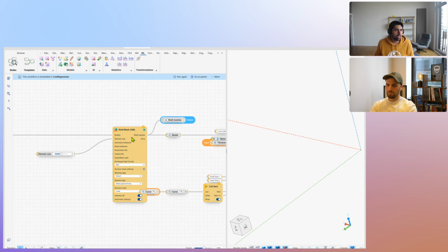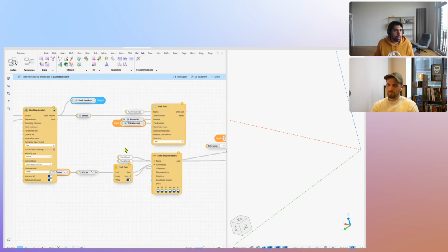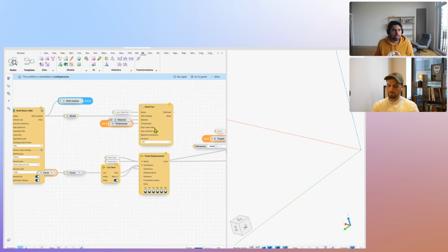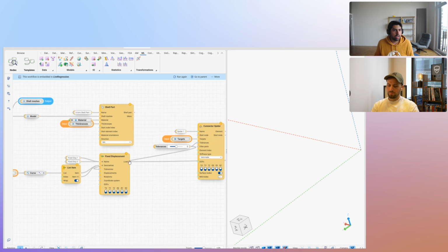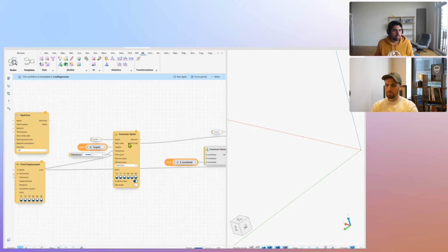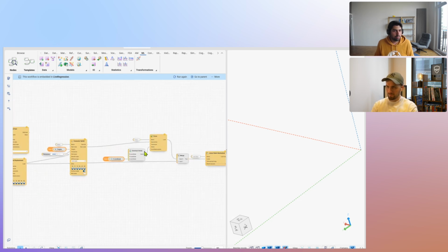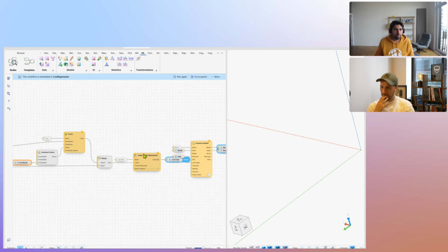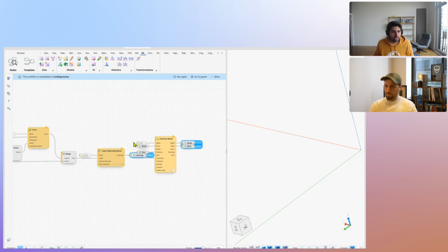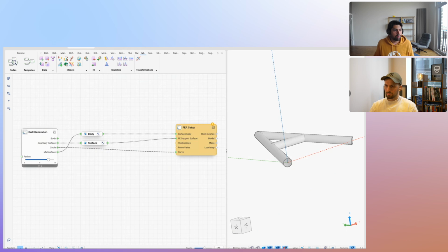And what this is doing is basically it's taking the body. I use HyperMesh to mesh it. I basically declare it as a shell part. I apply some fixed displacement. I also can build my RBEs, apply the forces, do a linear static step, and construct this model. Basically build the load step.